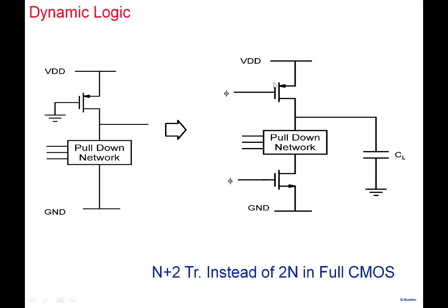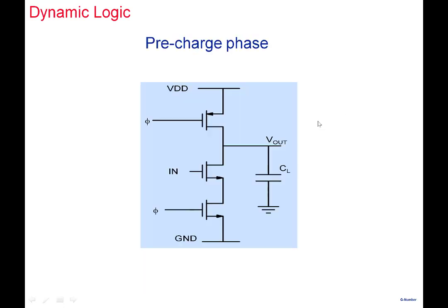Now we note that either the pull up here is on, which is simple, or the pull down is on. So it's no longer a ratioed logic. It's ratio-less. So you can choose any size here and any size here. The output value would be the right value of 0 instead of some non-zero value here. So both these disadvantages of this particular logic you can see here are overcome in this particular one. No static power dissipation, and it's a ratio-less logic here. But then these advantages that you see here, they are coming at a price.